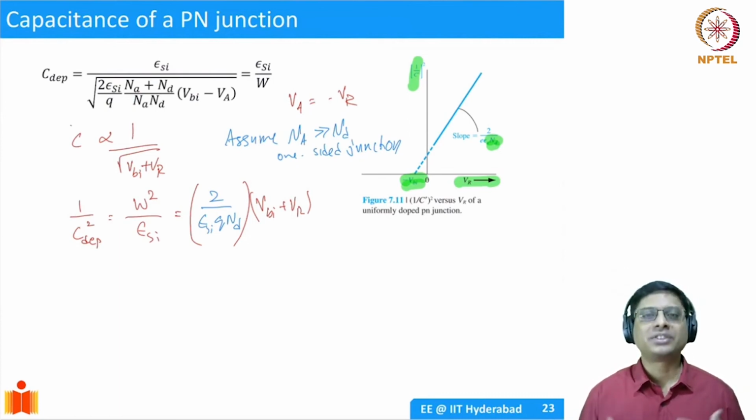If I do that, the capacitance is going to be large, and because of it, it's going to be slow. And this is one of the reasons why semiconductor devices, over the last 50 years, have been continuously shrunk in size. So much so that today we have MOSFETs in 5 nanometer or 7 nanometer technology. So they're very, very small devices. The reason for that is once you make it smaller, the capacitance reduces, RC reduces, so that circuits are faster. That's one of the primary driving forces.